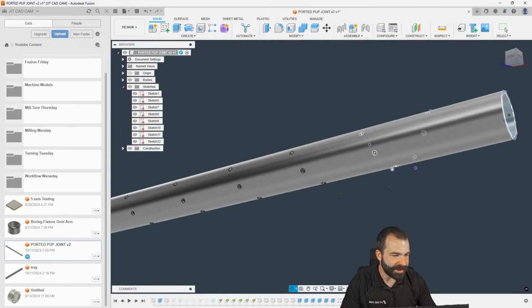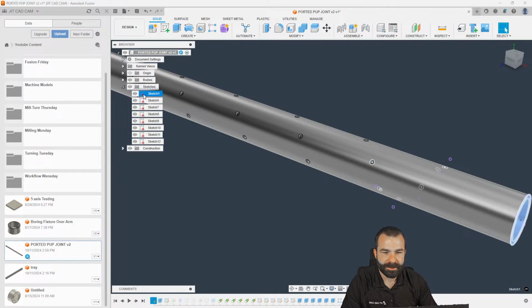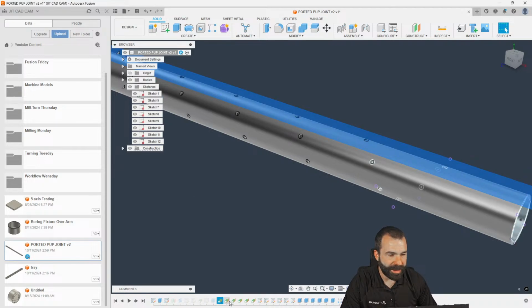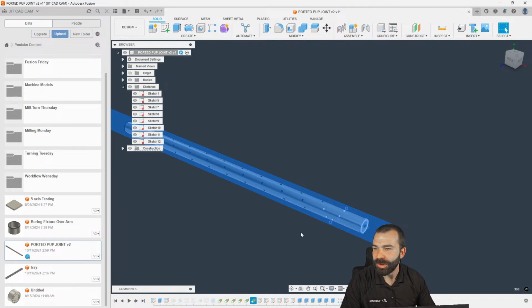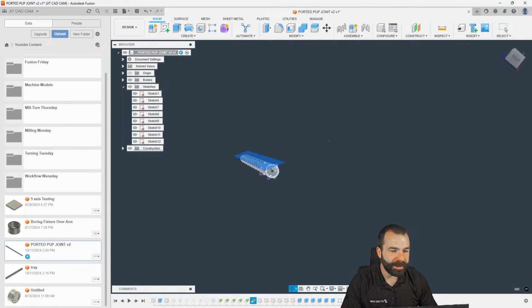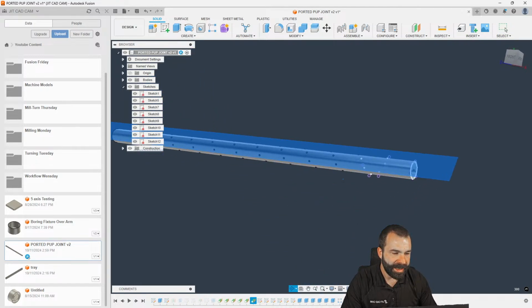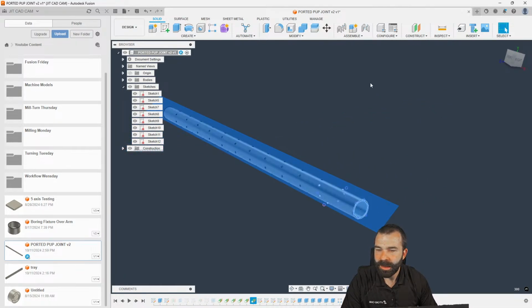So what I'm seeing is it looks like you projected. All right, so you created planes at angles, and then you created a sketch, and then you extruded that into your part, right? Completely doable that way. There's no right or wrong way to do something like this by any means. And then it looks like once you created one loop, you basically had what you needed.